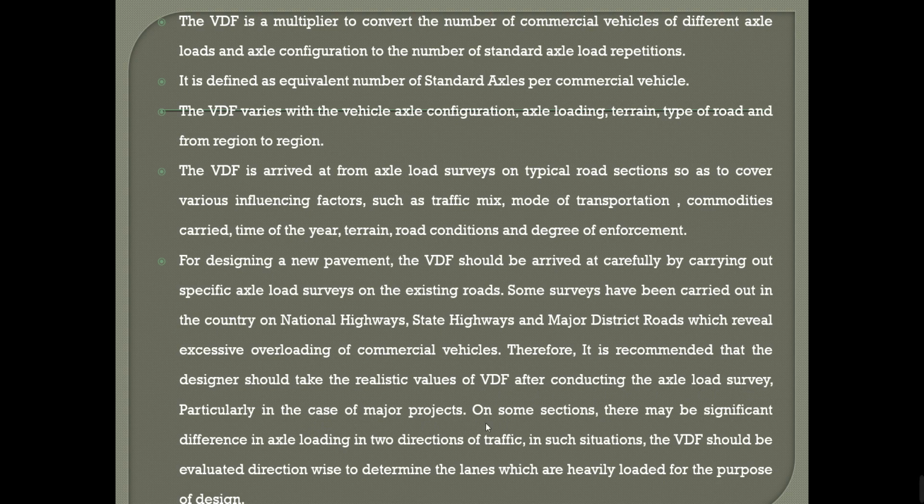On some sections, there may be a significant difference in axle loading in the two directions of traffic. In such situations, the VDF should be evaluated direction-wise to determine the lanes which are heavily loaded for the purpose of design. As you know, in Indian road conditions, you will experience most vehicles being overloaded beyond the axle load capacity of 8 tons. Hence we do the axle load survey for all the vehicles running upon the national highways, state highways, and major district roads.